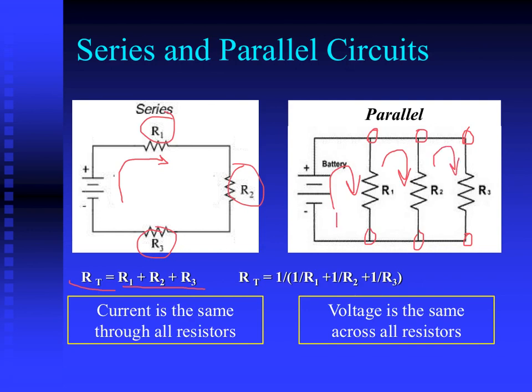So you have in essence I1, I2, and I3. Each one of those currents will be different based on the resistor in that circuit, because you have 3 different circuits. Each circuit only has one of the resistors that you had in the series circuit. So you can see the load, or the resistance in each circuit, will be less than in the series circuit.